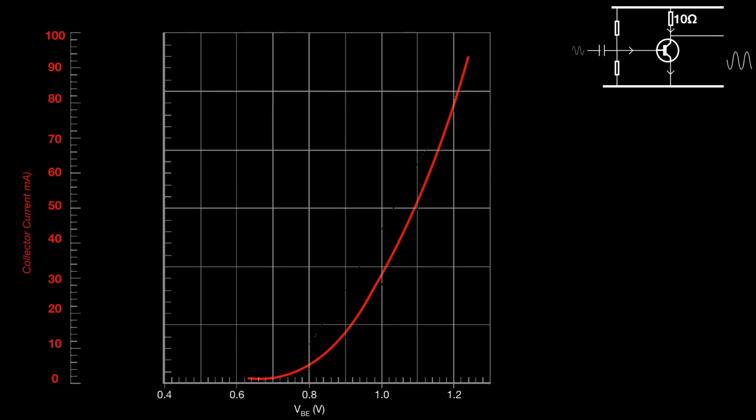Let's have a quick look at this then. This is the curve that we've been able to draw now for a while, with collector current IC on the vertical axis and base emitter voltage on the horizontal axis, and there's the curve. And you can see for this transistor, the knee develops slightly later than for the previous examples.